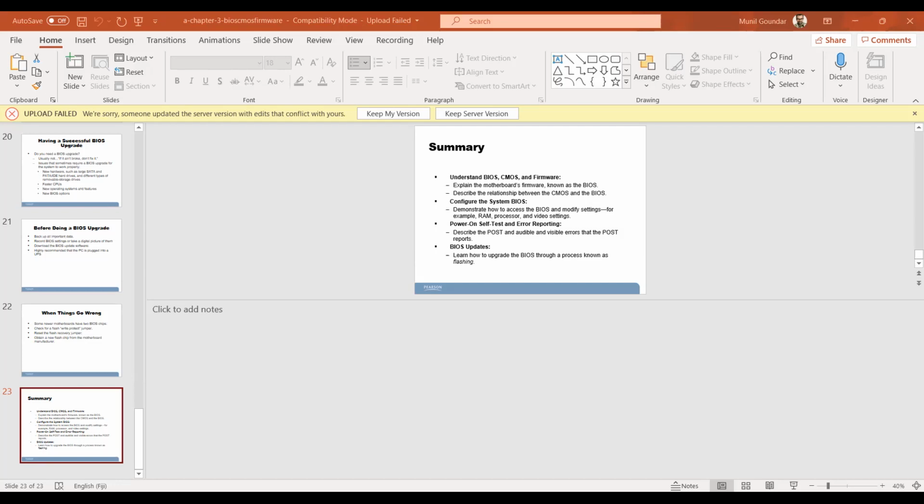Use the recommended voltage level for the memory installed if your system BIOS setup permits voltage adjustments. Install additional case fans over or behind the location of the memory modules to pull hot air out of the system. Keep air intake vents in the front of the system clean, and replace any defective cooling fans.